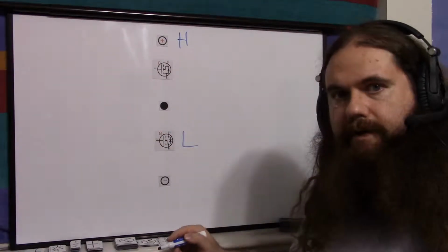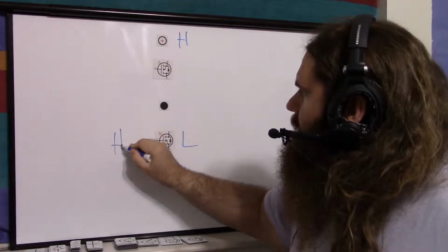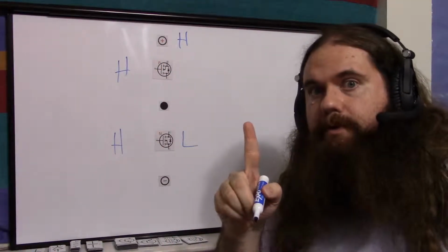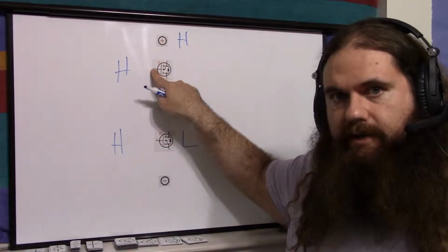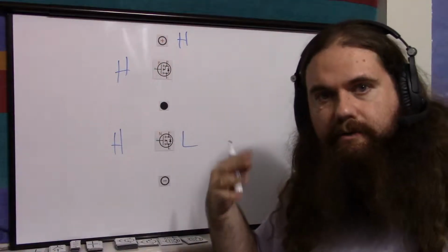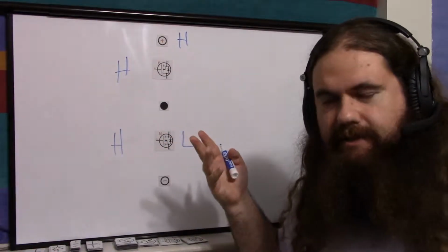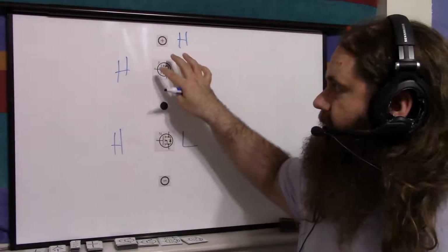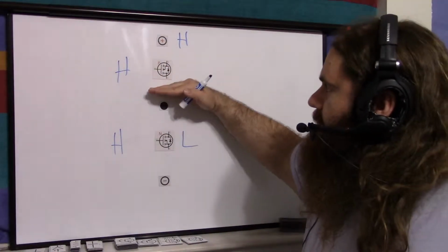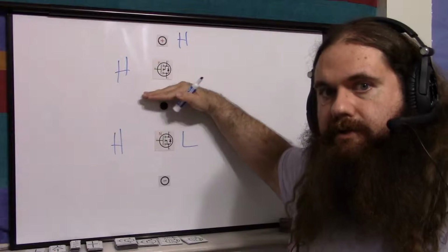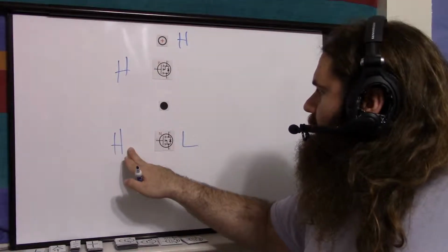So let's say our input is high. So let's do high here and high here. It's an inverter, it's one input going into both of these. Well, we've got high on the source and high on the gate, so the gate capacitor, quote unquote, the gate capacitance, will discharge because there's no voltage across that. And this MOSFET will turn off, which means drain is a floating output. There's no conductance.